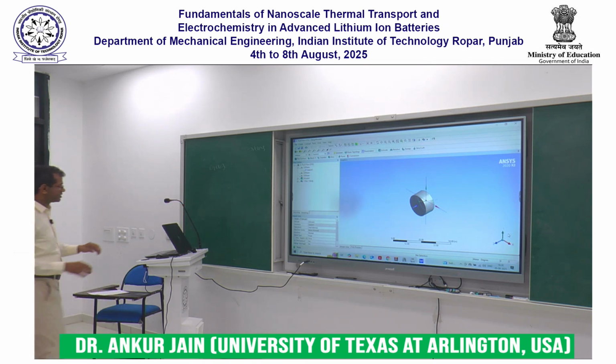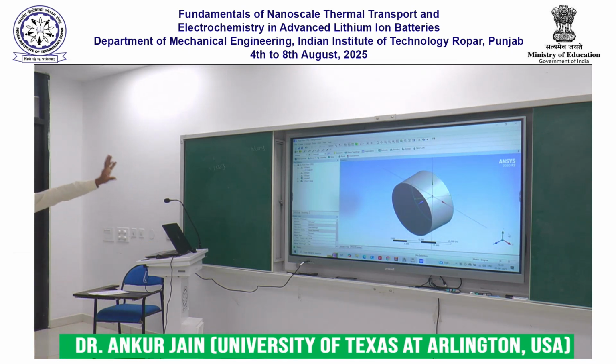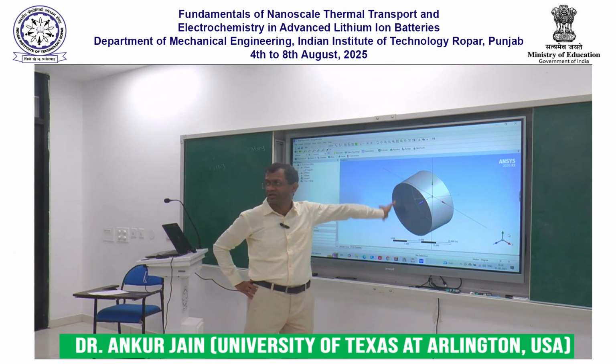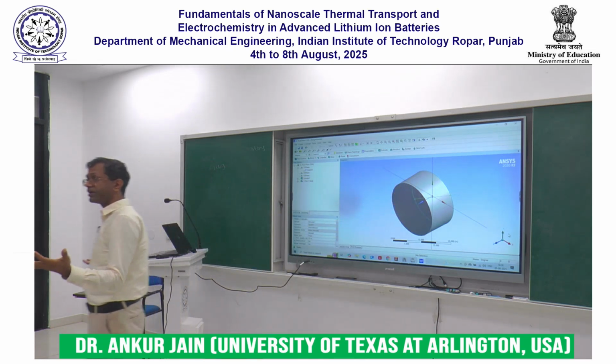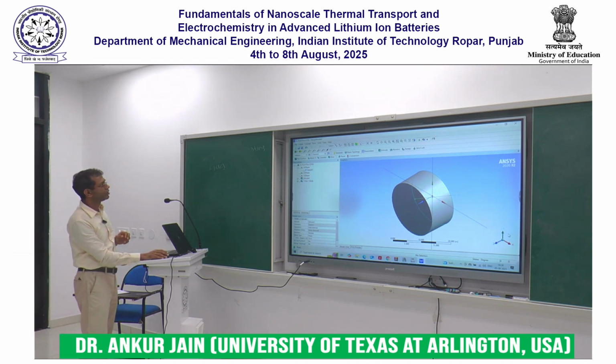This is a very simple geometry, of course, and so I was able to create the geometry in this body. I can do a little bit of geometry development inside this tool, but for more complicated geometries, this also makes it possible for us to import an external file. So if your geometry is available in SolidWorks or CATIA or any other CAD tools, you can always import it into this environment.